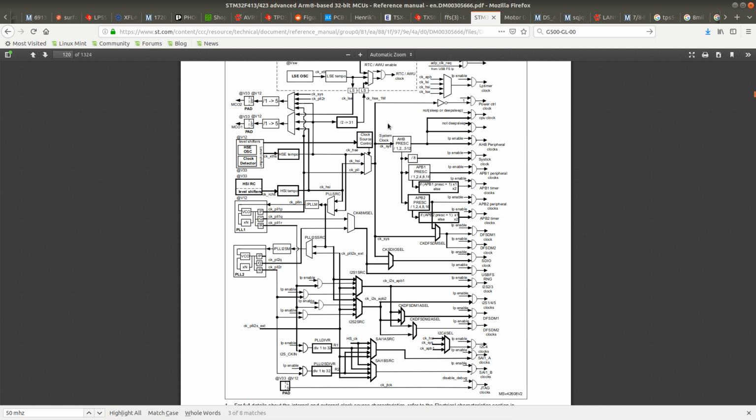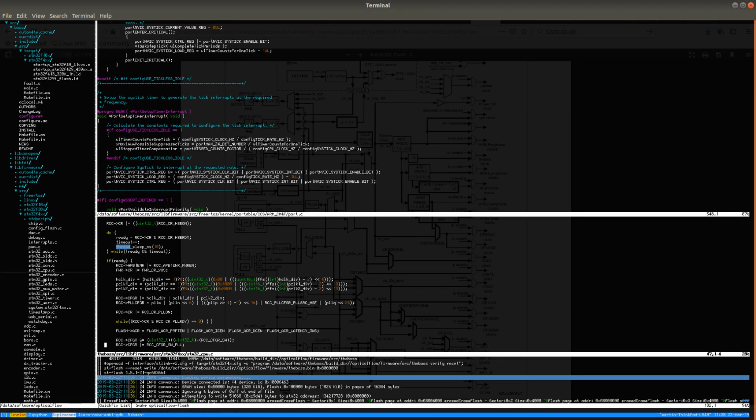And then we get system clock, which goes to the AHB prescaler, HPRE. And SysTick clock is for some reason divided by 8. But SysTick comes actually after the AHB prescaler, which means that it should possibly be using a different value for the clock.